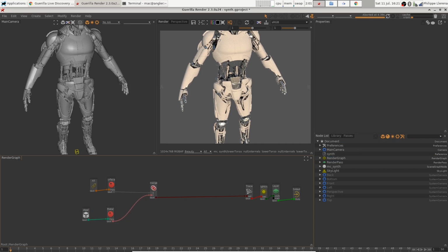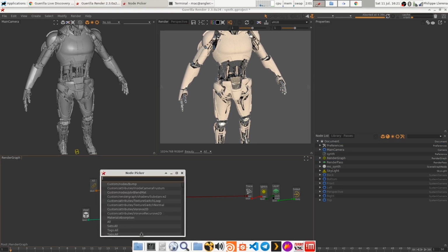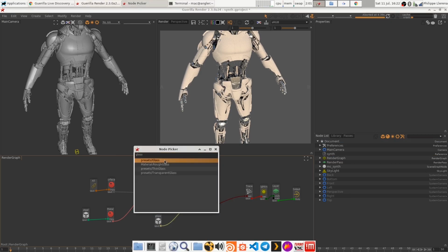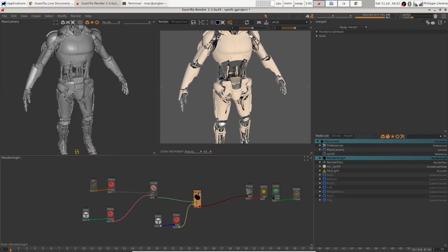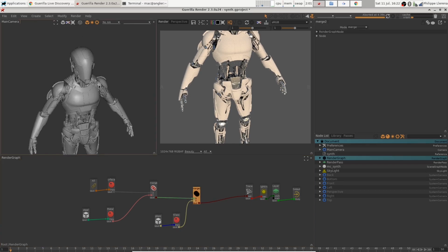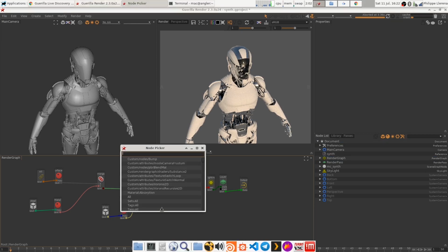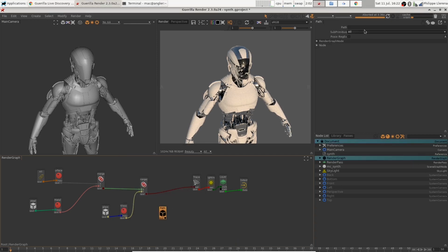So we can still work with overrides and select some elements. I'm going to create a new path node, and search for the glass elements, connect it to the flow, and create a glass pattern with a glass preset, which is a simple glass surface transmission shader, nothing fancy, and you will see that I start to get my look development. Let's create another one with the BL